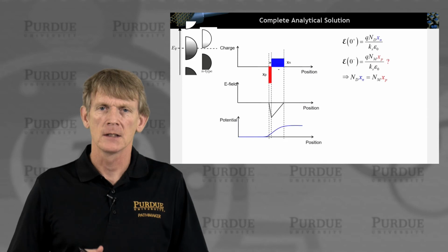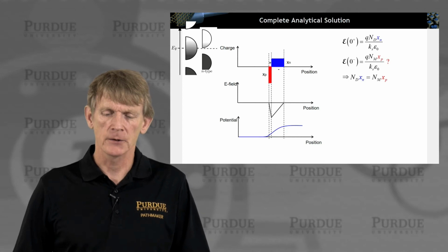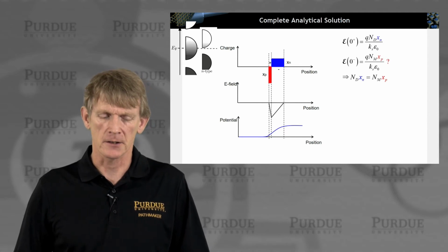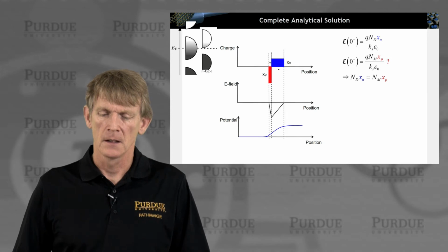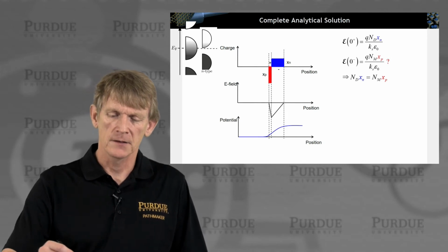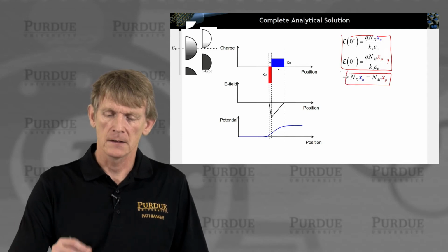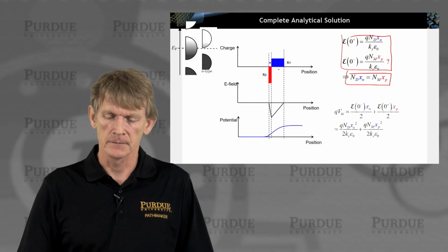Why can we neglect this potential drop in the metal, and do the same kind of graph that we've shown here before, as if it's a normal semiconductor junction, and we'll try to figure out how big this Xp would be. All right, so by displacement field continuity, we have the charge balance as well in this red area and the blue area.